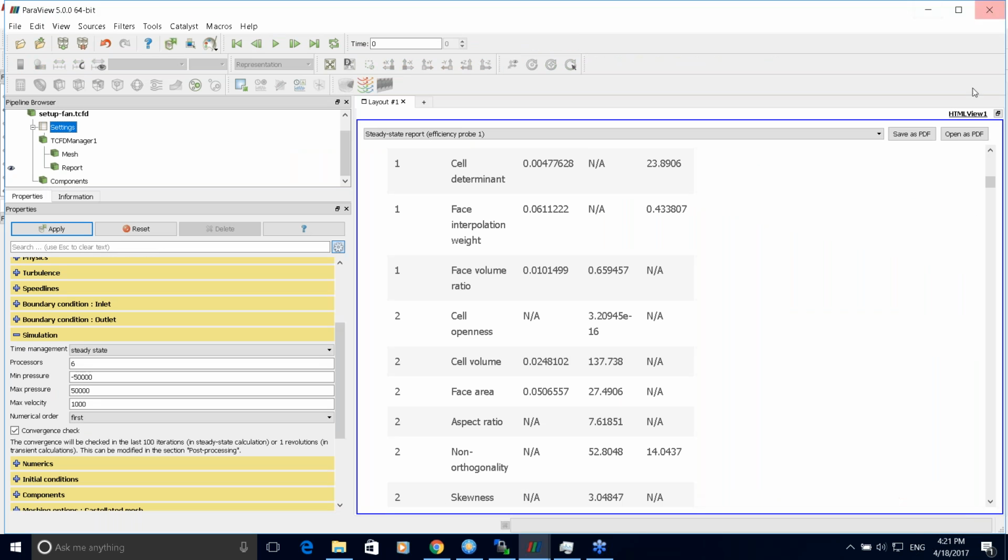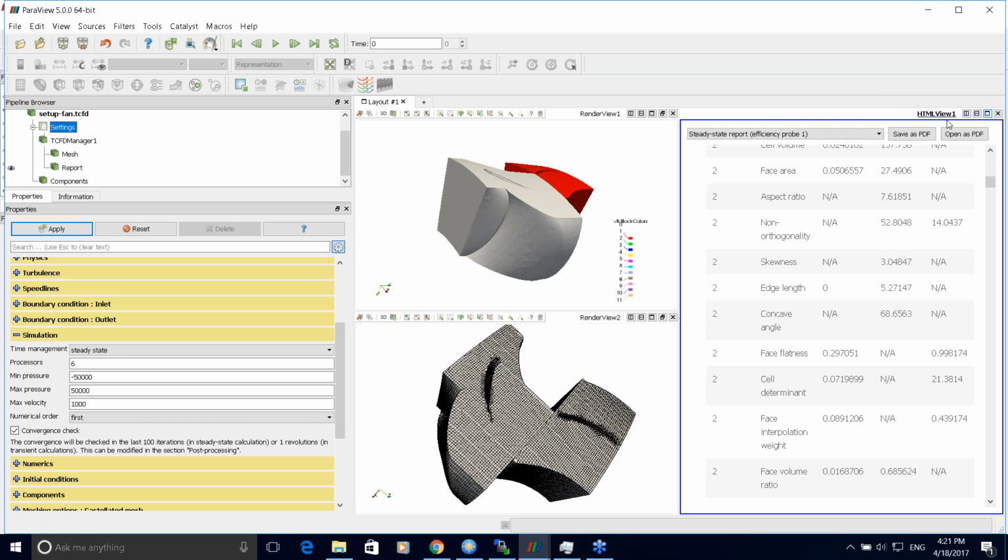Yeah, of course. So it's this, and the second last question is on Radek. Can we vary the temperature of the flow as it passes through a multi-stage simulation? I don't know if I understand it well, but basically if we compute it in the compressible mode, yes, you can. With compressible simulation, we have the temperature field, so we can see the temperature drop through the passes, through the multi-stage simulation.